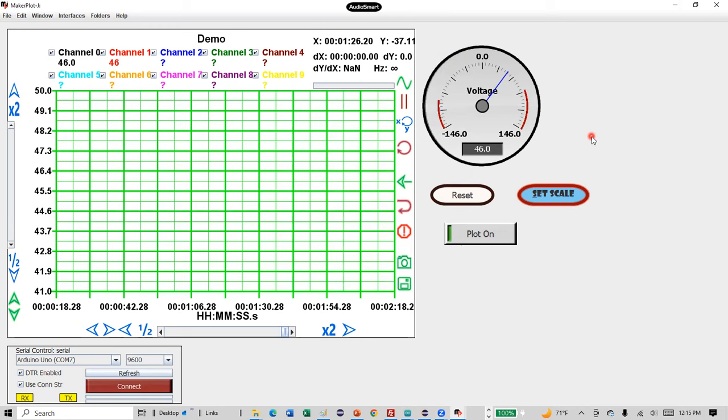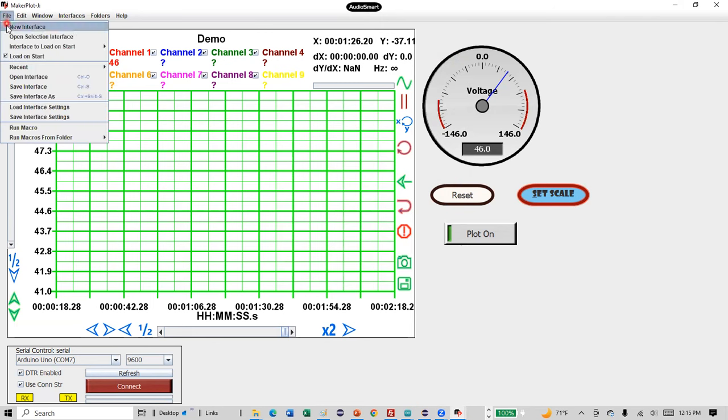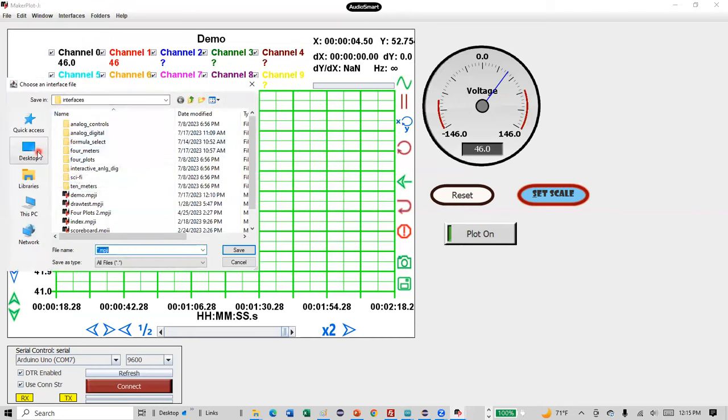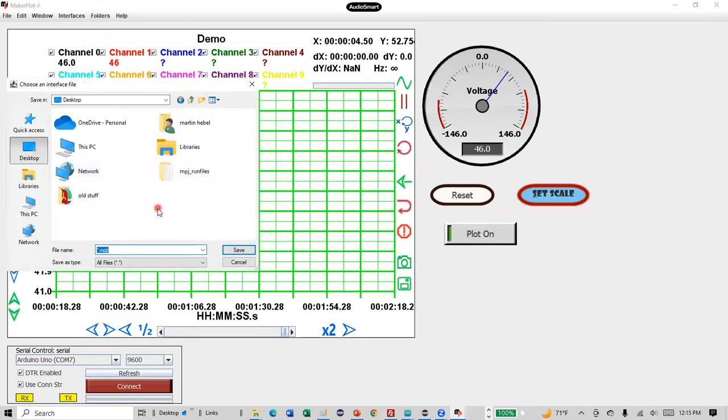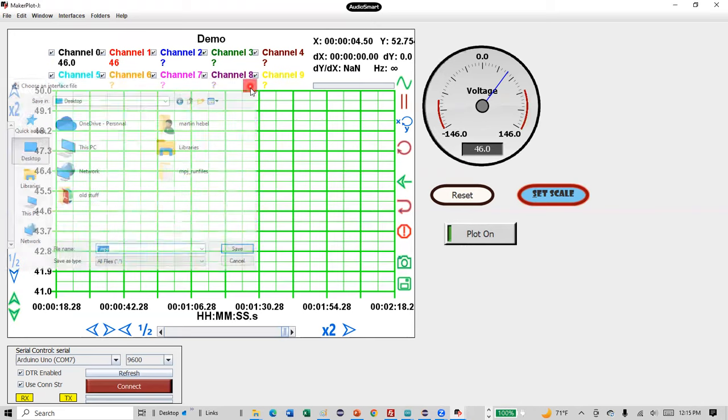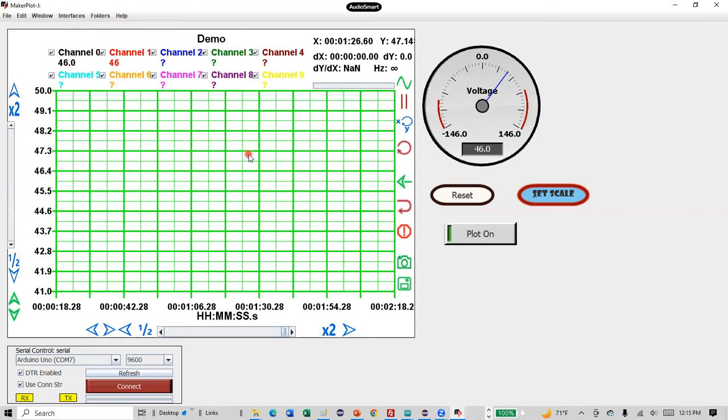One note: if you do use your own graphics or sounds or things like that, what you want to do is do a file, save as, and put that somewhere you can find it easily, like on your desktop, and create a new folder for it. Put all those images in that folder first before you apply them to your controls. Then when you build it, it will use a path instruction to access the location of that image file, of that media file. And that's how you make distributed controls. It's also discussed in the help files.